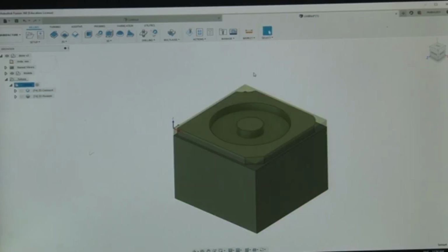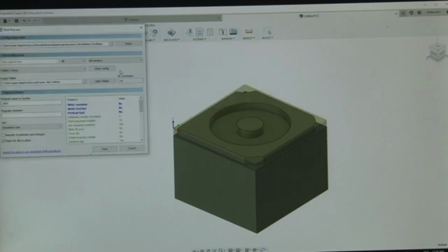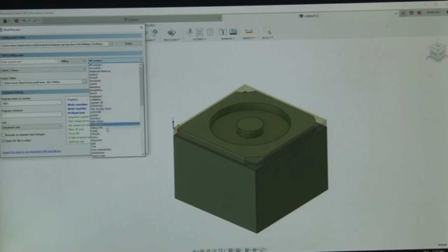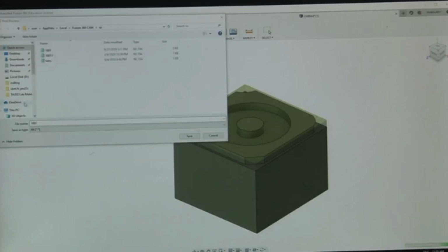Now we generate the codes. So depending on the surfaces that have been generated, now the NC code will be made by this program, so that it can be executed in the machine. This is the program number, and we will post it. So we will save that program in a folder, in a file, and that can be called, and we can see this program.